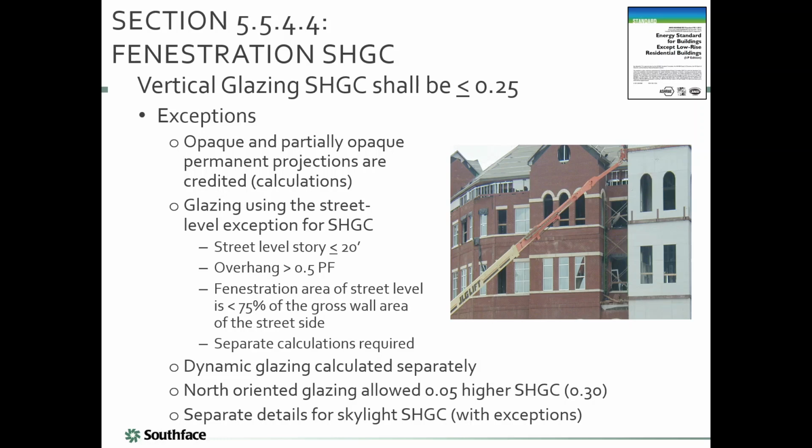This is really, I would say, more of an encouragement to the designer to try to lay out your building intelligently regarding the sun, which a lot of buildings don't pay attention to. But you really want to try to orient your building so that the vast majority of your glass is facing south or north. And that allows you to much more easily get and control natural daylight into the space.